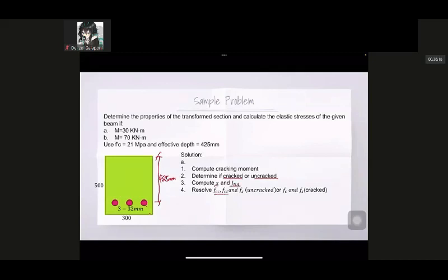So if uncrack, yung tatlo. If crack, yung dalawa. So parehas lang naman. Same, ang naibahan lang is the actual moment. So first, kung compute for the cracking moment, formula. So that is f cracking, M cracking, c_t, I_g, ano pa? f_r equals 0.62 square root of F_C prime.